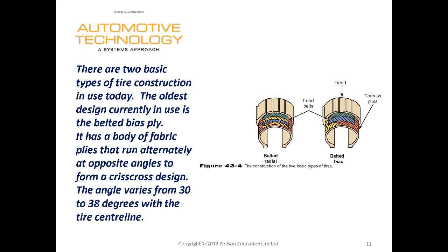Something to note, don't mix bias ply and radial tires. Not so common we're going to see bias ply tires these days, but they do have different handling characteristics. So make sure we either have 4 bias plies or 4 radials.